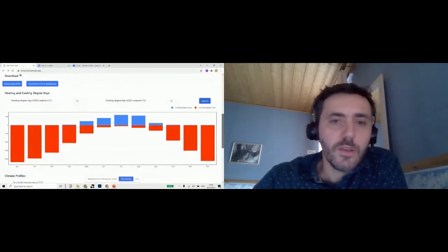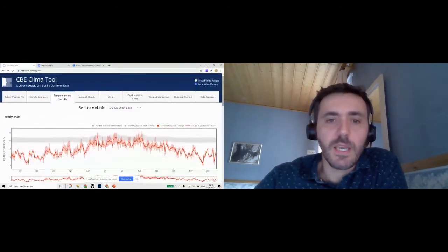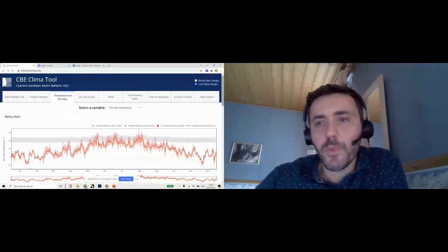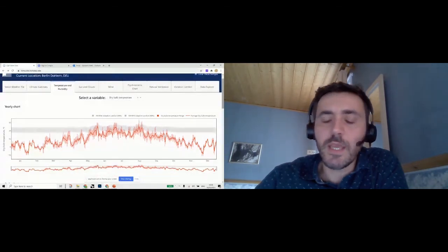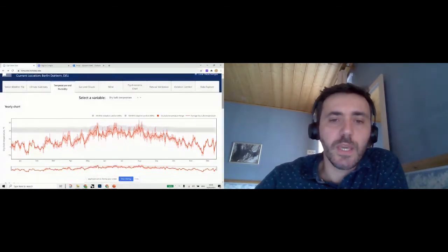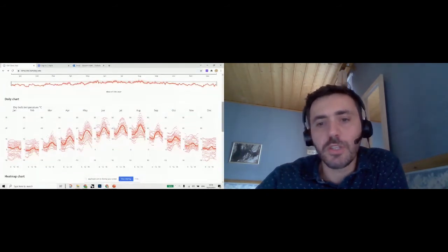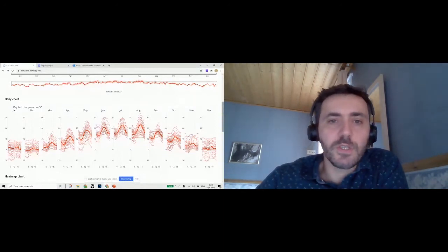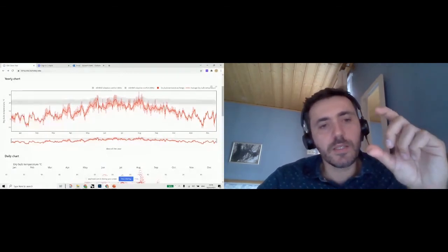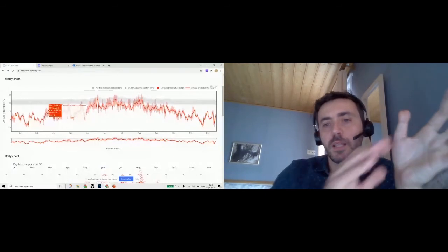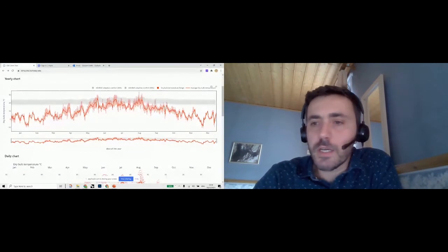Then moving on, we have the temperature and humidity chart, where you can see the temperature profile or humidity profile through this drop down. You can choose which one to display, and this one is showing the same data, but shown in 3 different ways. So you have first the average temperature for each day, and then just the bars that give you the maximum and the minimum. That's helpful to understand the range of temperatures over the whole year.